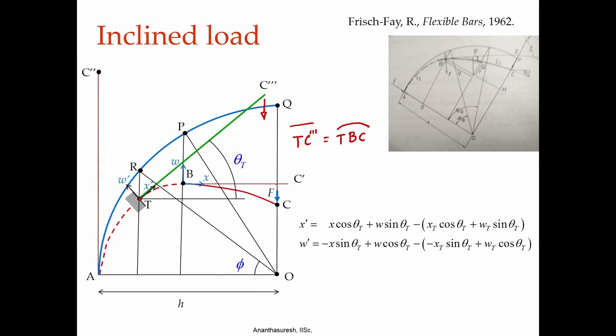If I have a horizontal beam of length BC prime, it bends like this. If I extend it, that is phi b that I have taken, all the way to 0, I get the rest of the curve. Any point T I take has a particular phi; I go up and join this line, I get this angle phi. From phi to pi by 2, I get the length TC triple prime.